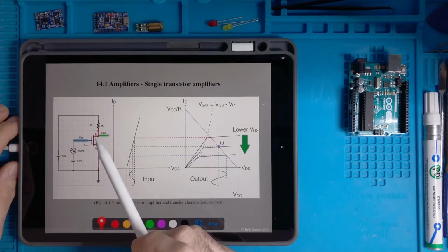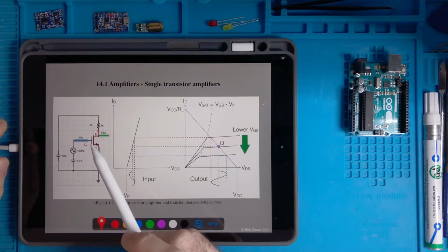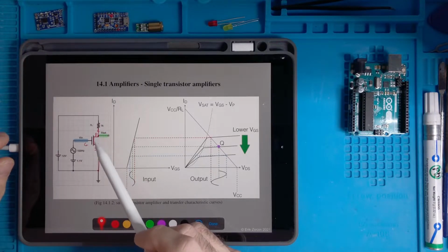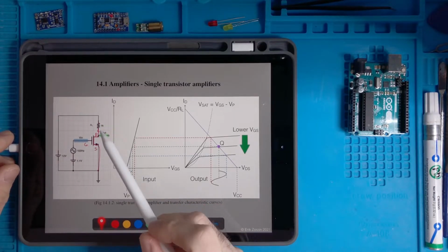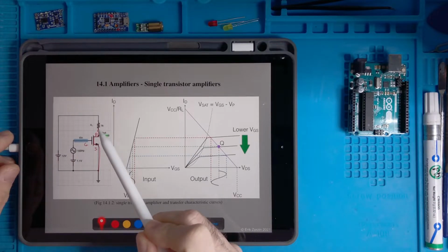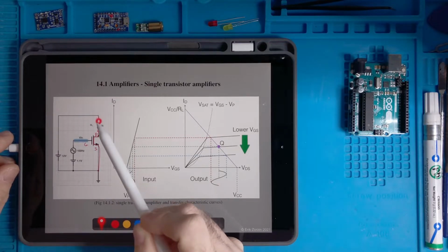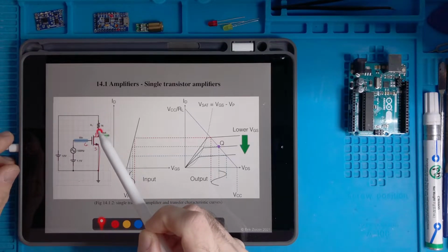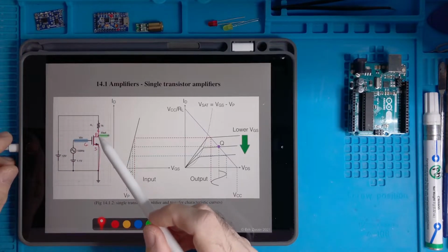So then we know that by changing the voltage at the gate, something happens. The channel inside the MOSFET gets bigger or narrow in a way that the current will change. So if the current will change, the voltage drop across the resistor will change. It's the Ohm's law applied to this resistor. Let's call it VR equals R multiply I. If R is constant and I is changing, it means that this delta V is changing. But if delta V across the resistor is changing, and this plus this must be always this because of the Kirchhoff's law, it means that also VDS is changing.